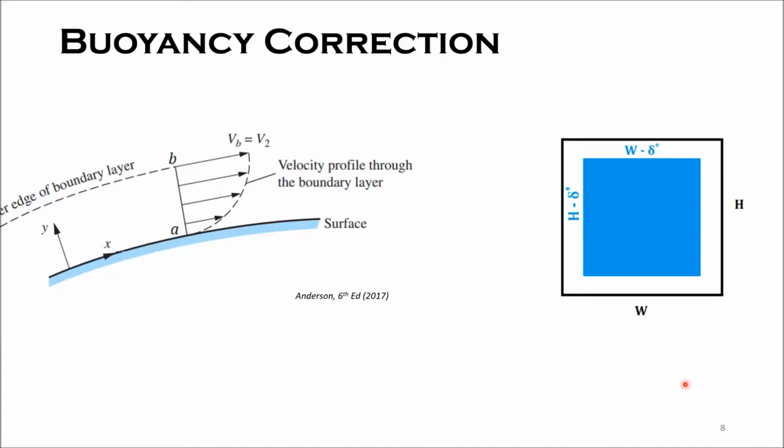From the continuity equation, we know that the reduction of area will result in an increase in velocity. Subsequently, from Bernoulli's equation, an increase in velocity results in a decrease in static pressure. This causes a horizontal pressure gradient in the test section from the entrance to the exit. Since force is a product of pressure and area, an increase in either of these causes the increase in force, which in this case is a horizontal drag force called buoyancy drag. The effect of buoyancy drag is to drag or pull the model downstream.